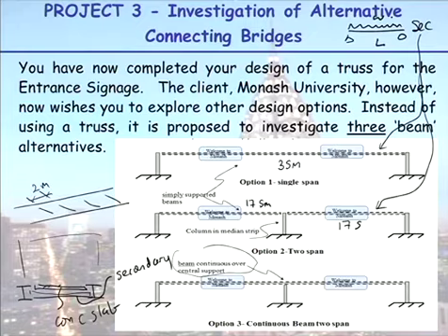So you don't have to keep on calculating. You don't have to draw me out 3 different bending moment diagrams. You calculate the bending moment once in terms of W and L, as a function of W and L. You have that in as an appendix or in the beginning. And then when you change from your secondary beam to your primary beam, you can say, referring page 1 again, moment is equal to whatever WL, and you substitute in the new value of W and the new value of L. So people that aren't here are going to do pages and pages and pages because they're going to put all the numbers in. And especially you have to iterate your beam size.